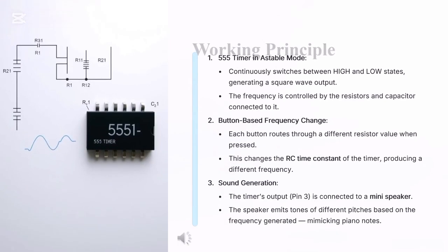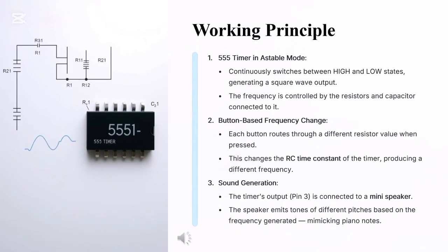In this circuit, the 555 timer IC will work as an astable multivibrator, producing a square wave of different frequencies at the output. The speaker will produce different sounds depending on the frequency of the signal. To change the frequency of the output signal, vary the total resistance of the circuit by pressing different switches. So every time you press a button, a different amount of resistance gets connected to generate a different frequency square wave, and the speaker will produce different tones.